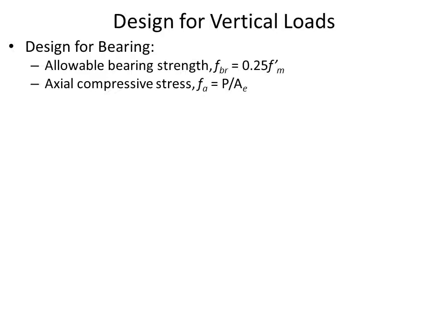The bending stress, as you know, has a positive and a negative sign because at one side it will be tension, at the other side it will be compression. So it's plus or minus My over I. Again, this is something that you should know from mechanics of materials.